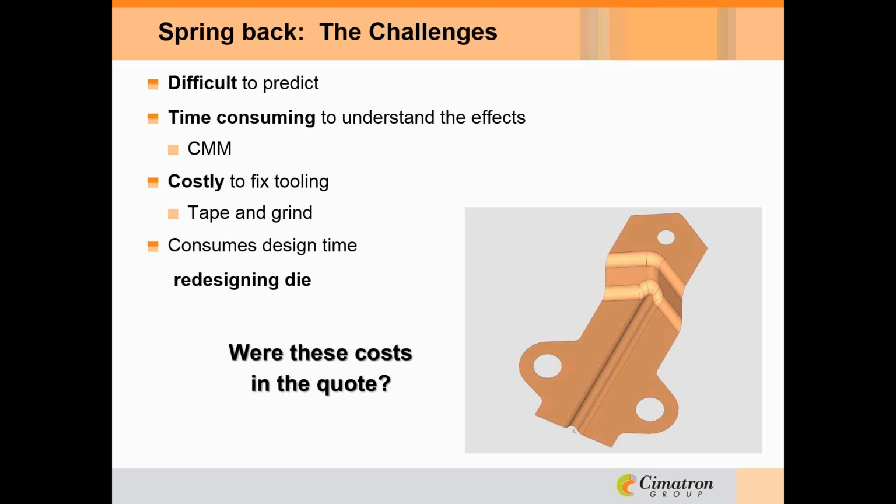Okay, let's talk about springback. Everybody knows about it. It's probably one of the greatest factors in turning out a good part, to be able to compensate for springback. Even an experienced designer with years behind him can find it very difficult to understand and predict exactly what springback is going to do. We know springback, as the simple explanation, as the metal's resistance to being formed as it wants to adhere to its original shape.